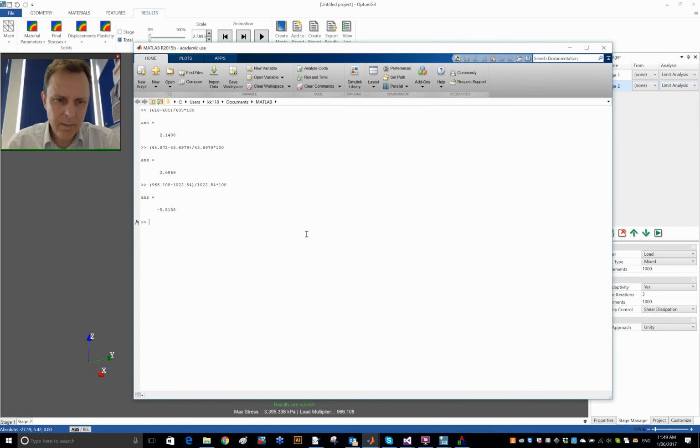So a bit more than twice as much roughly as in the undrained case, and that's not really unexpected. And there is of course also, as our friends in Sheffield Limit State have pointed out, and often do point out, and I think rightly so, one possibility is to measure the error with respect to the actual final limit load. Another possibility is to measure the error with respect to the input, with respect to the friction angle.